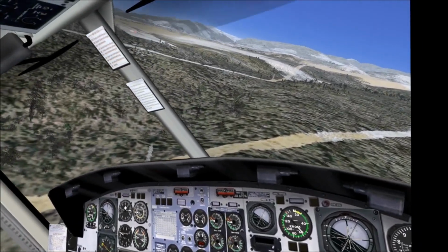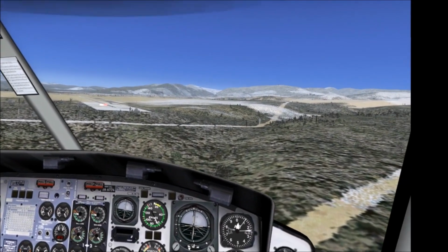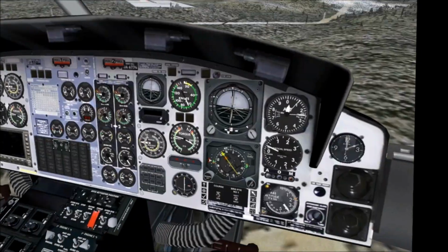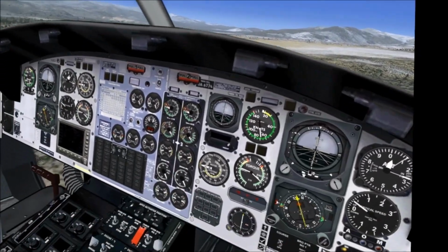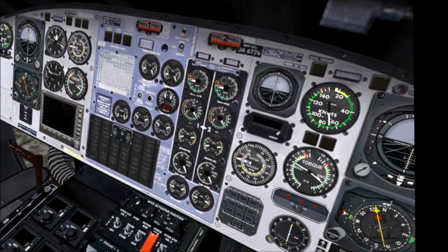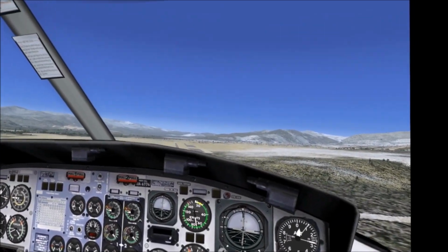So, would we get a dual engine failure for doing that? Probably not. Would we get a rotor RPM droop? Absolutely, as the engines began to limit. And I would expect our ITT to get higher, but for some reason it wasn't.